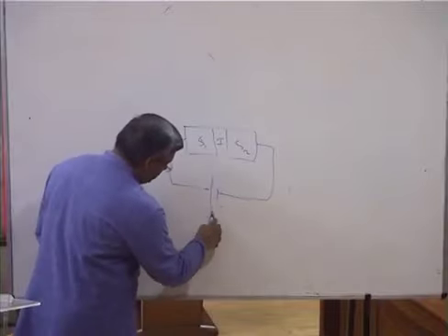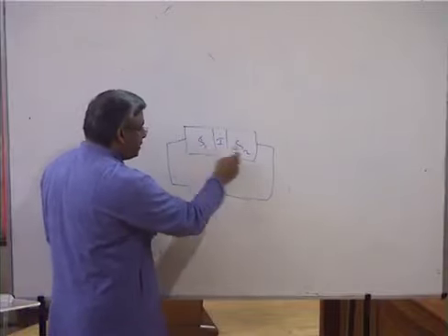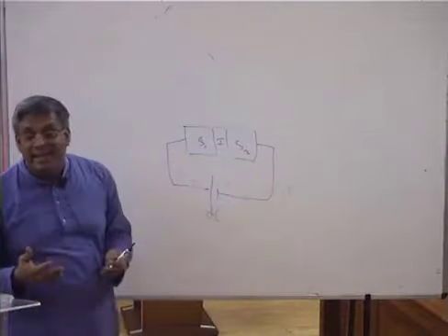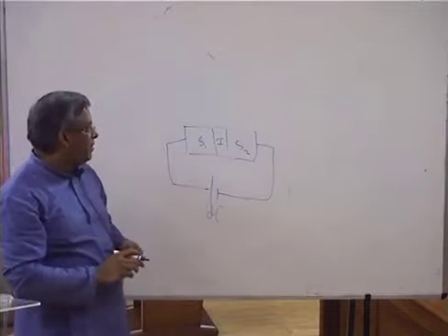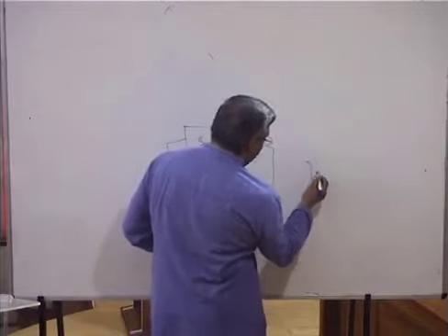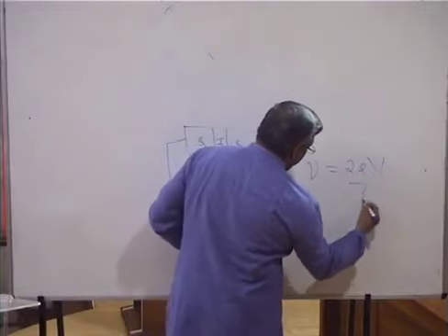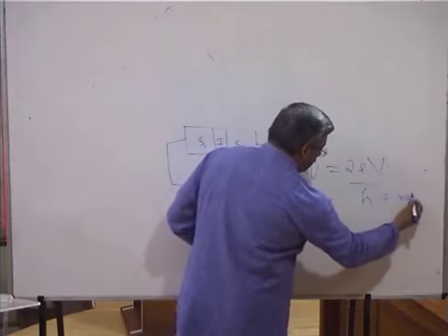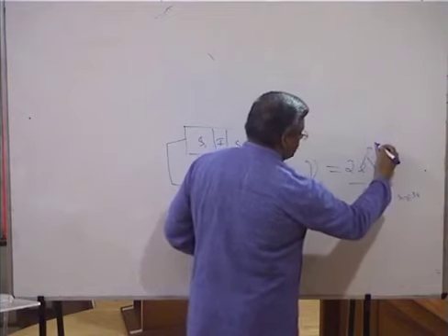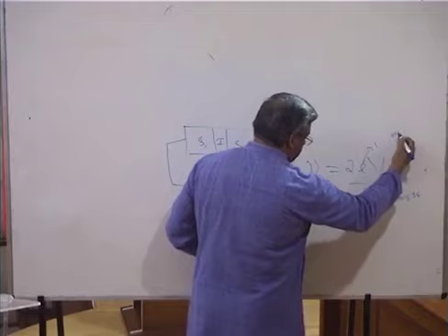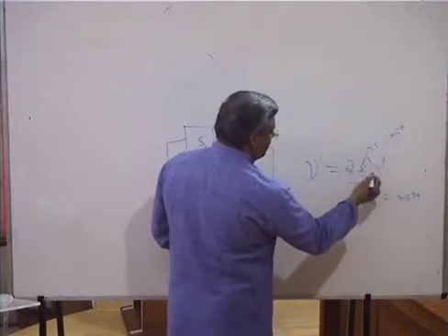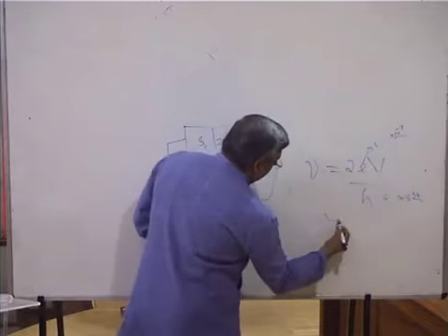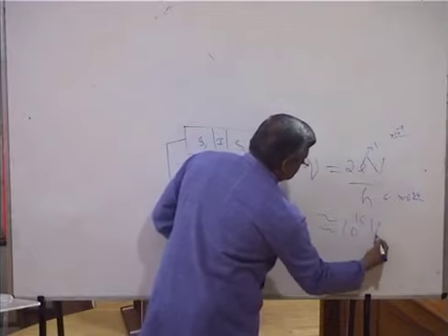Of course, you have given DC here, but the current gets oscillating through this particular junction, and it became AC, not just an AC, but with a tremendous value for its frequency. So the frequency was defined as 2eV divided by h. h, you can imagine, has a value of 6 point something times 10 raised to minus 34, and the electronic charge is 1 point something times 10 raised to minus 19. So depending on the voltage, it will have minus 34 in the denominator, minus 19 in the numerator. So it will be of the order 10 raised to 15 hertz.